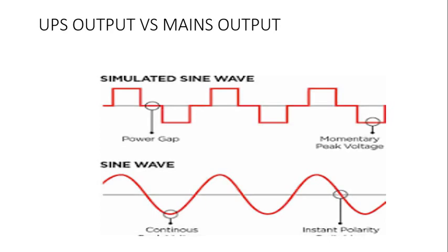The induction motor is designed to operate on this regular voltage waveform, whereas the UPS output is a quasi square wave. So during power outages, when the UPS supplies a quasi square wave, the induction motor runs with noise. This sometimes becomes a nuisance.